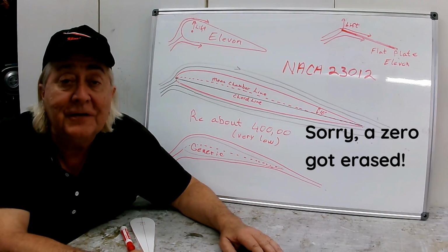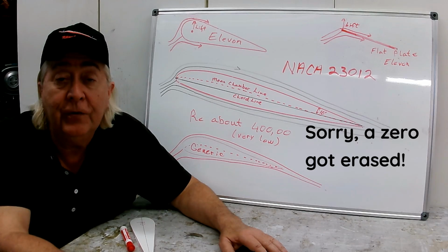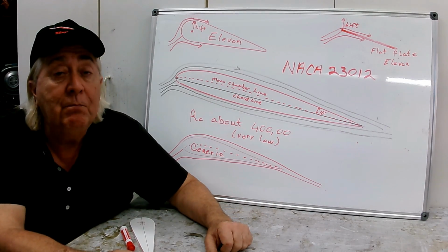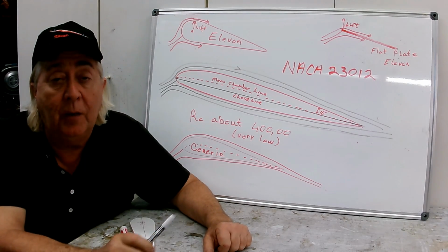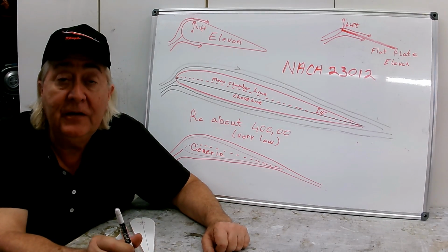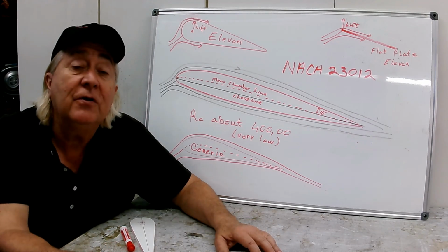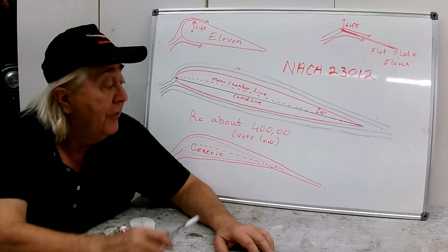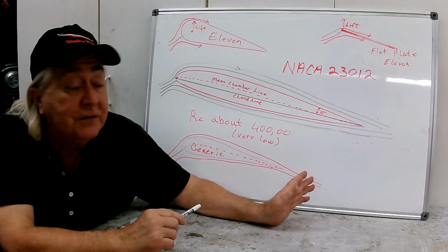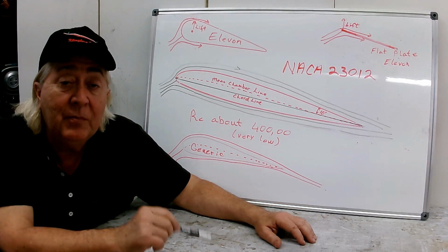None of them work. And the reason they don't work is because all of those standard answers are for standard flight conditions, quote unquote standard, which are much higher Reynolds number, 1 million and up, where flow behaves completely differently. And the models that I built and other flying wing models work great because they're all down in the laminar flow region. They're below this 400,000. So I'm working in a region here, and most of our hang gliders fly in and out of this region where there's not a lot known about the aerodynamics.